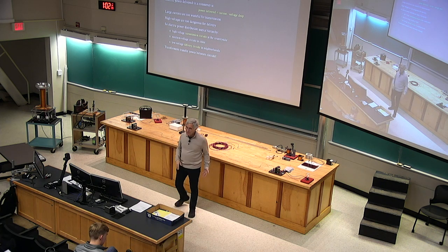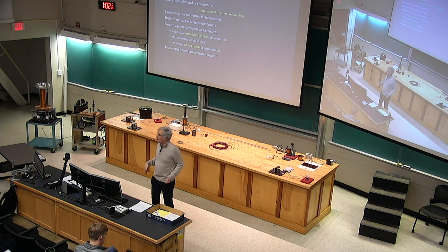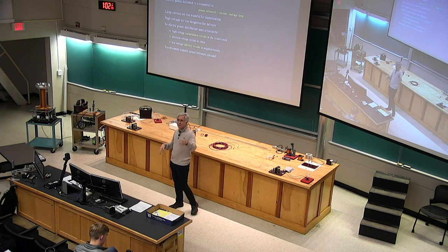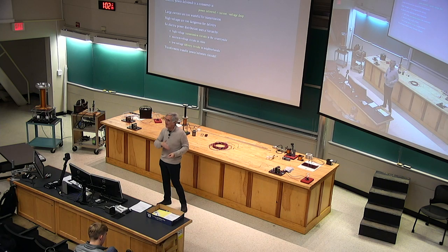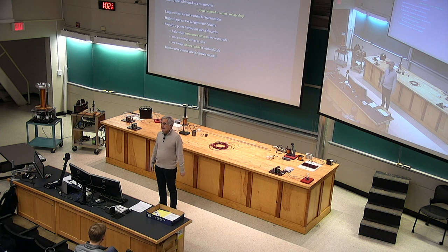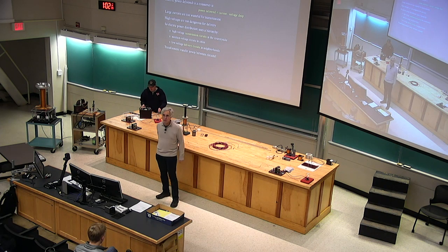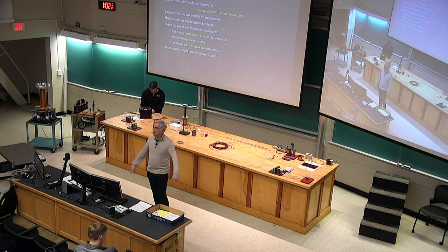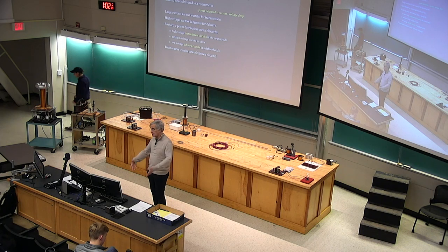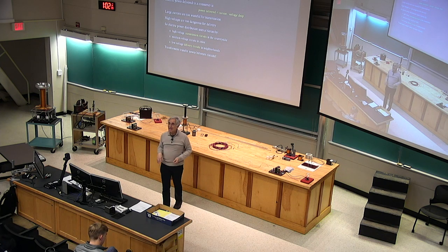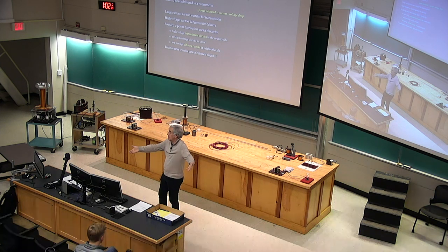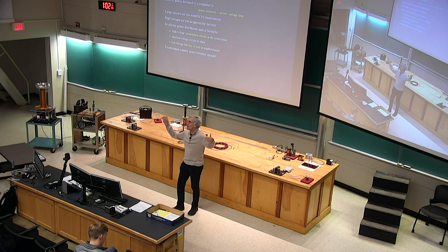So the other extreme is go for a big voltage drop. Send the charges out chock full of energy per charge. That is big voltage, high voltage. And take them back at very low voltage. So that each charge drops off a lot of energy, and then you don't need as many charges going by each second. You're using each charge more effectively. So a small current with a big voltage drop. And the product of voltage drop times current is big again, yay, lots of energy delivered. And so these two approaches look seemingly indistinguishable. Who cares? They're both fine.